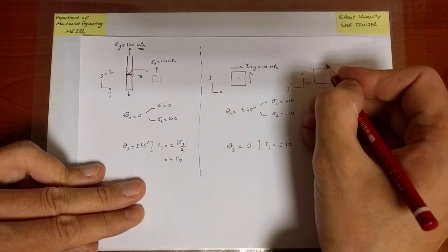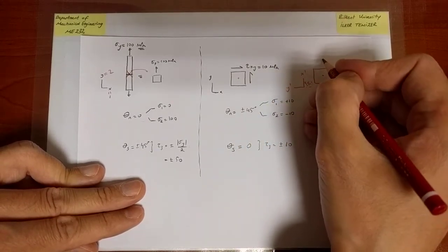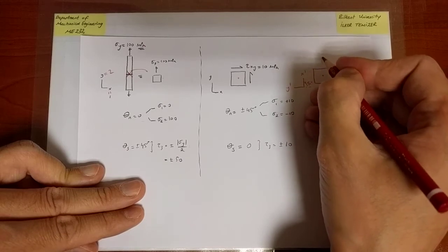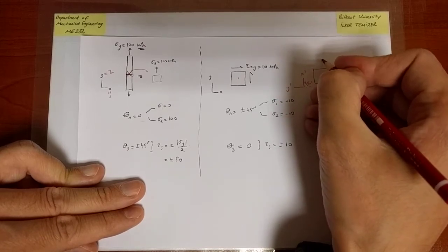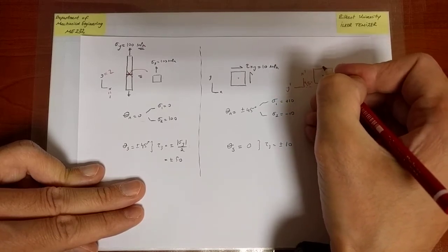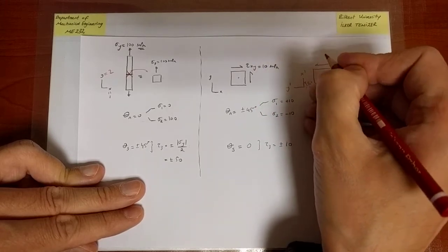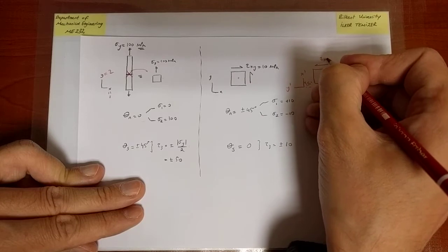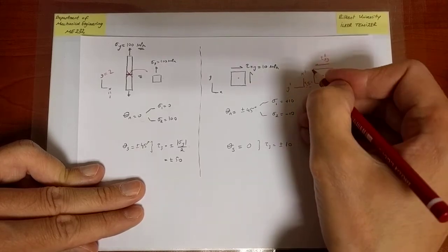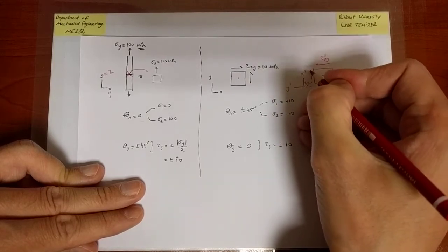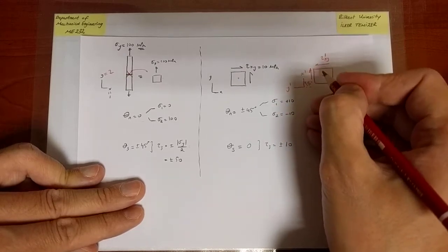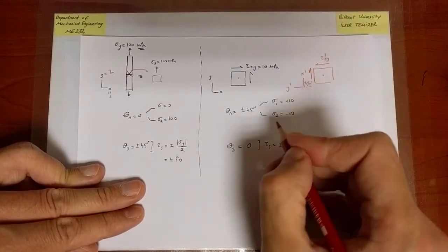So remember, according to my orientation, the normal stress is going to be sigma x prime. The shear stress is on the plane with x prime in the y prime direction. It is tau xy prime. And on this plane as well, there's going to be the same thing of the same value, and it goes without saying I have the same things here.